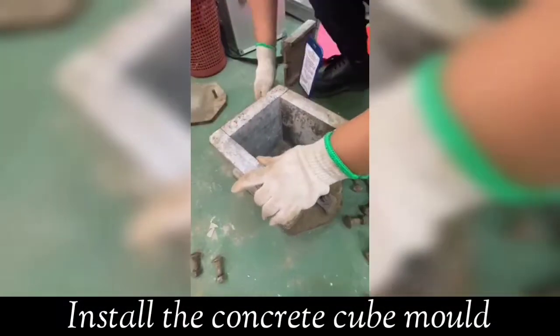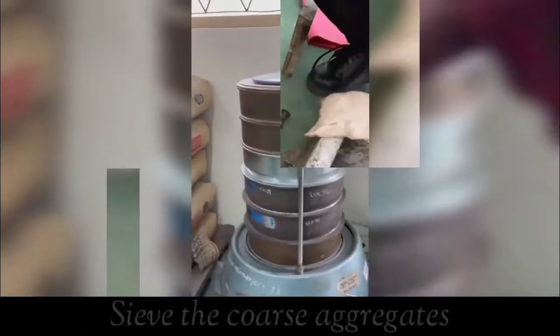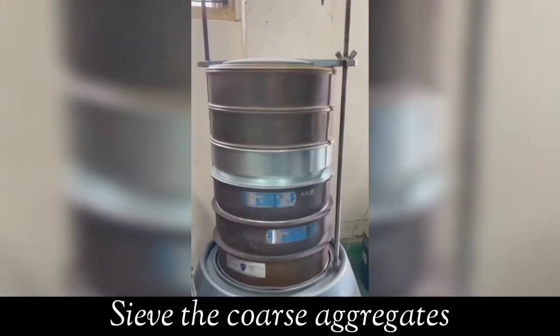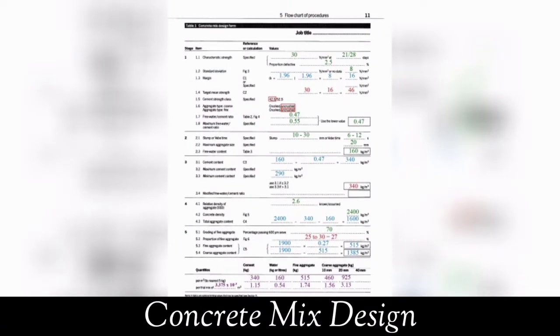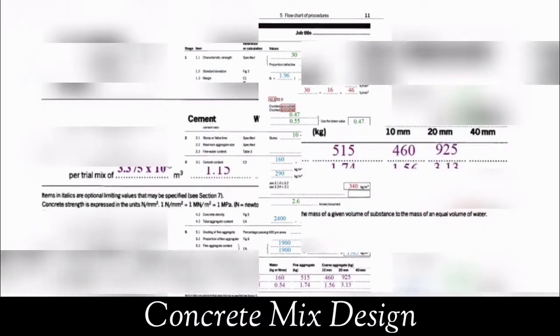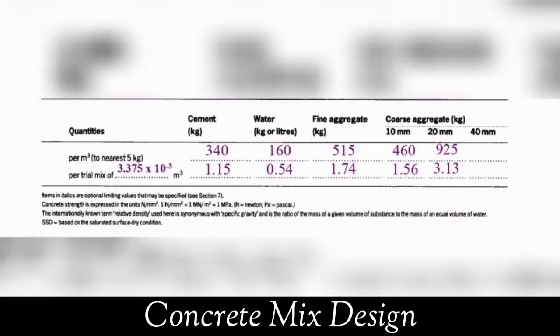First of all, install the concrete cube mold. The coarse aggregate is sieved to get 10 mm and 20 mm coarse aggregate. Based on this concrete mix design form, we can see the weights of materials that we need for our concrete mix. We need 1.15 kg of cement, 0.54 kg of water, 1.74 kg of fine aggregate, 1.56 kg of 10 mm coarse aggregate and 3.13 kg of 20 mm coarse aggregate.